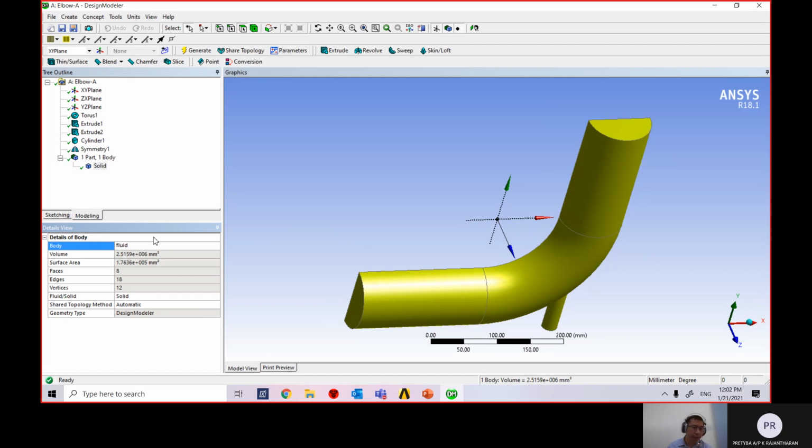Key in the fluid there, and then go to the setting here. Remember to change this one. Although you change the name, the computer in the setting is seeing this one as a solid. You need to left click and then drop down, go to select fluid, so that in the simulation, the software itself knows that the body represents fluid rather than solid.